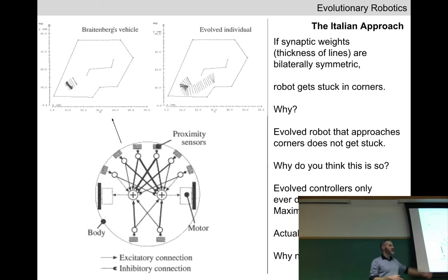So a robot that's traveling at 80 millimeters per second takes a snapshot of all of its 8 proximity sensors, moves 80 millimeters per second, and at the next update of the sensors, it's already crashed. So who knows what that refresh rate is? Doesn't matter. Evolution says I can really only travel at 48 millimeters per second given the slow refresh rate of my early 90s sensor technology here.